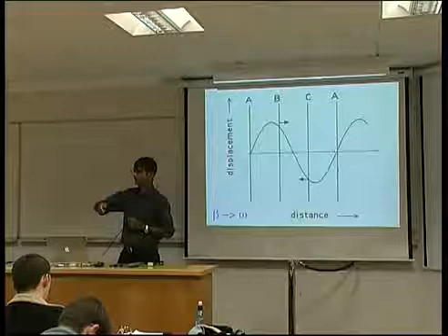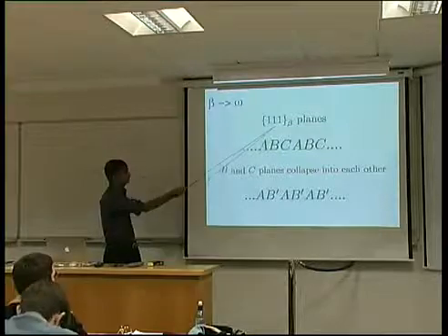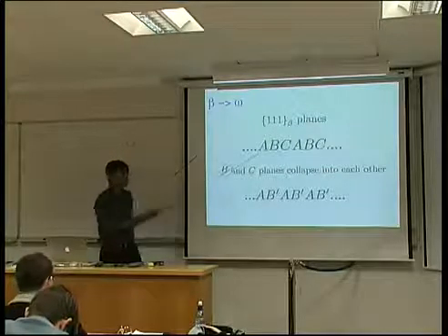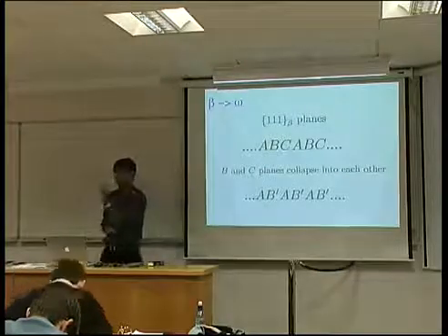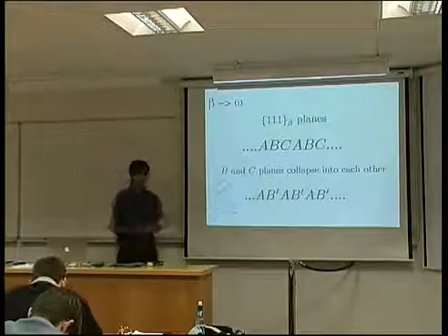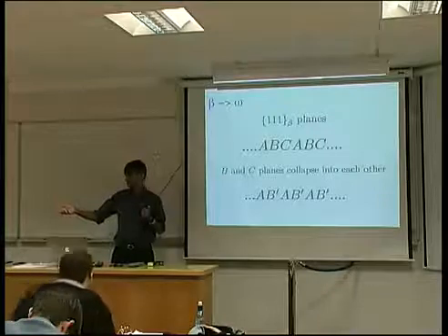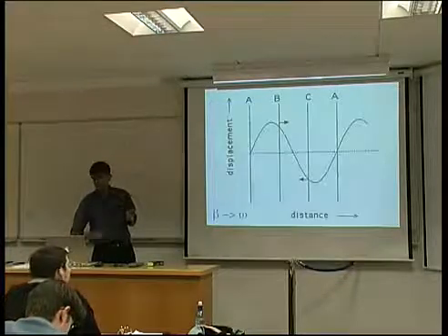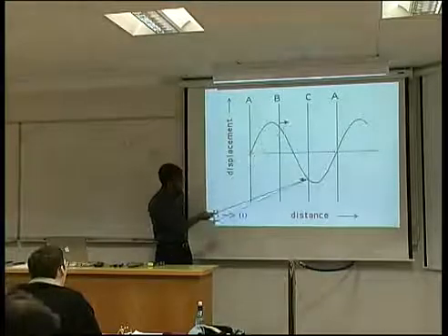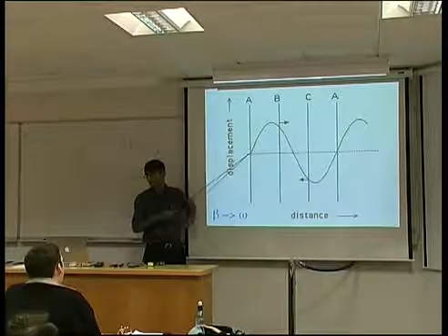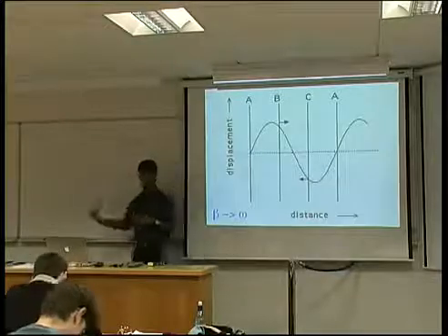So you can imagine that's a very strange transformation where you take the 1-1-1 planes of beta, which are stacked in ABC sequence, and a pair of those planes collapses to give you an AB dashed sequence, because it's now got double the atomic density. And you can see why I'm using a displacement wave, because here this is being pushed in that direction, and this is being pushed in that direction, and that's at a node, so there's nothing happening there. So you can describe it in terms of a displacement wave.